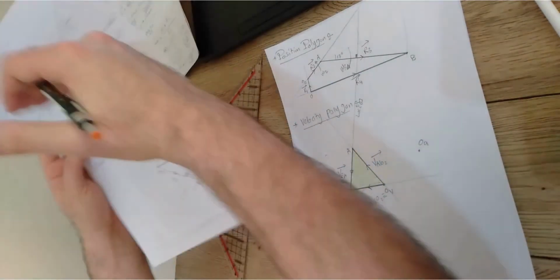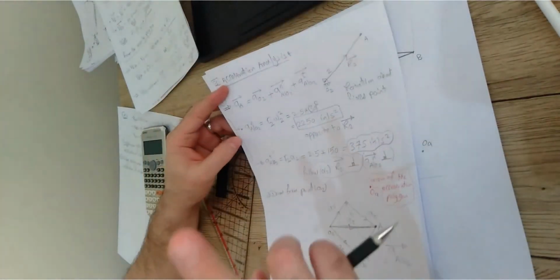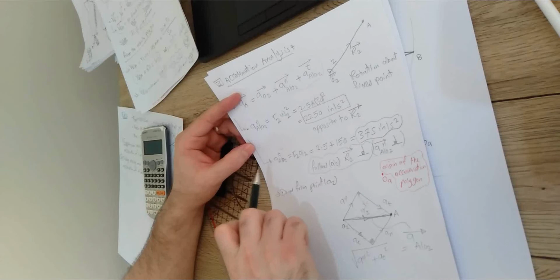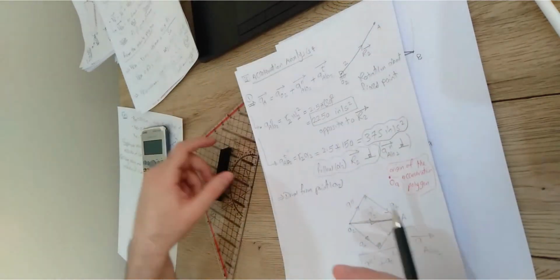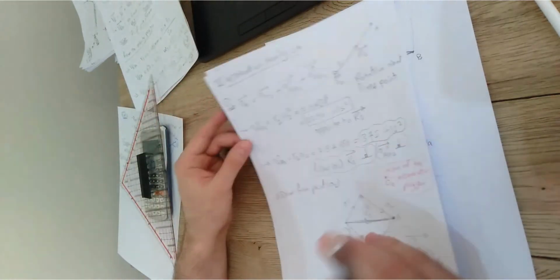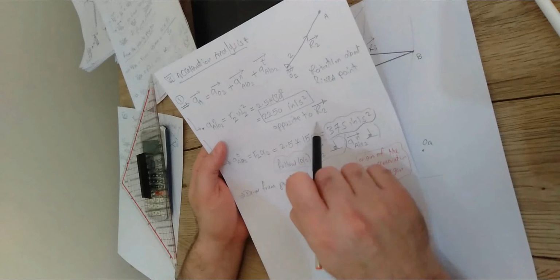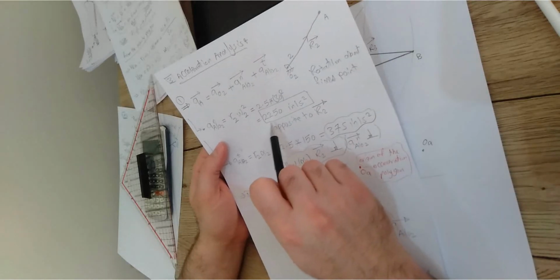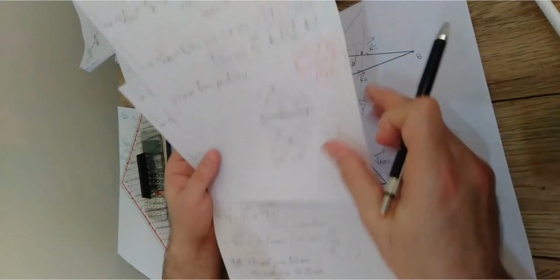Then I'm gonna stick to the plan, starting with the first line here. For the first line, I'm going to draw two components. One is normal, then the tangential, or you can start with the tangential, then the normal, as long as both are known. But conventionally, as we agreed, the normal all the time will be known, so it is better to start with the normal. I'm going to start with the normal, and its direction is opposite to the R2. This is its value, which is 2,250, which I'm going to draw as 90 millimeter.